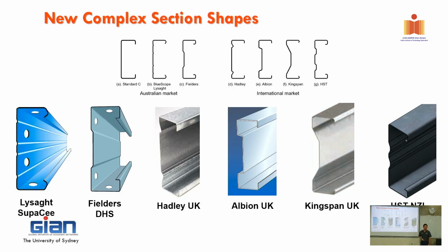If we couldn't get the best benefit of high strength steel, why make it so strong if its failure is at maybe half of the stress? The only way they can improve is to increase the buckling loads by introducing those stiffeners. Those stiffeners will push up not strength, but buckling. And the buckling, as you learned from the previous lecture, plays a role in the strength equation at the end.